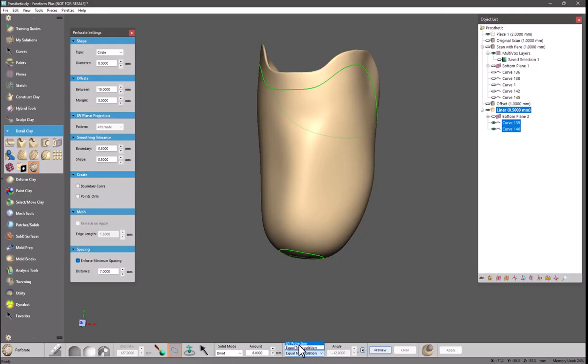We have something that's called UV projection, so this is going to try to unwrap and flatten the selected region, and this often provides much more uniform and consistent results, but it has a couple limitations to how it can be created. Right now, this being a fully cylindrical type of shape, there is no way to flatten this out and have something that can be mapped to a flat object.